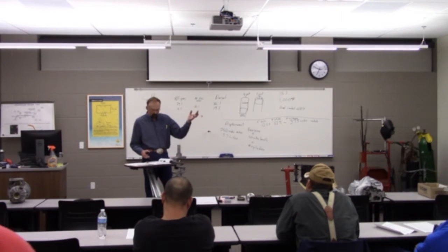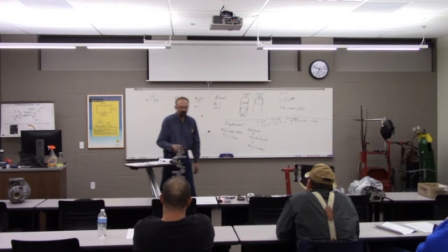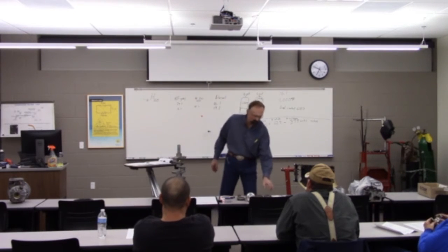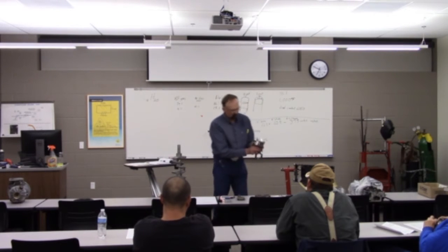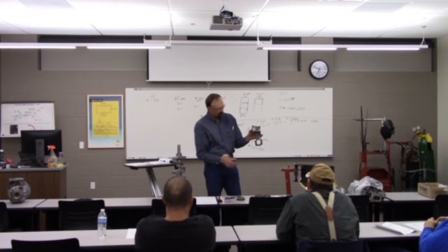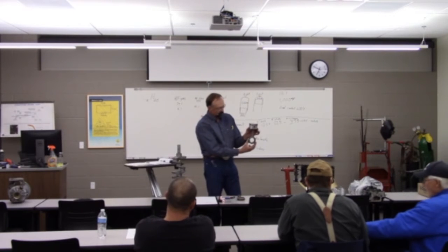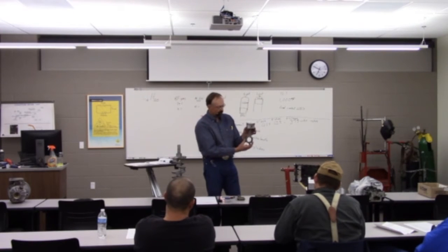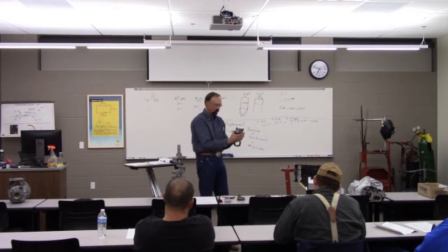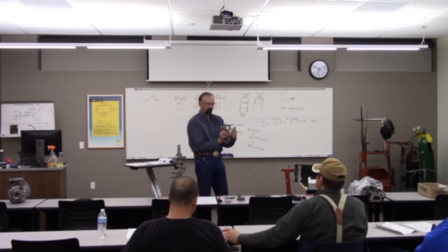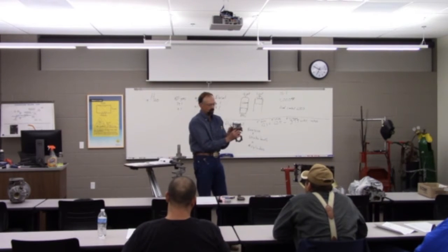So we talked about the piston moving up and down and the crankshaft, but we need to connect those two, right? So that's why we call that a connecting rod. I've got one here that I've put on the piston. And you can see that this needs to swing back and forth because we want that piston to go straight up and down in its bore and have pretty tight clearances between this piston skirt and the cylinder walls.